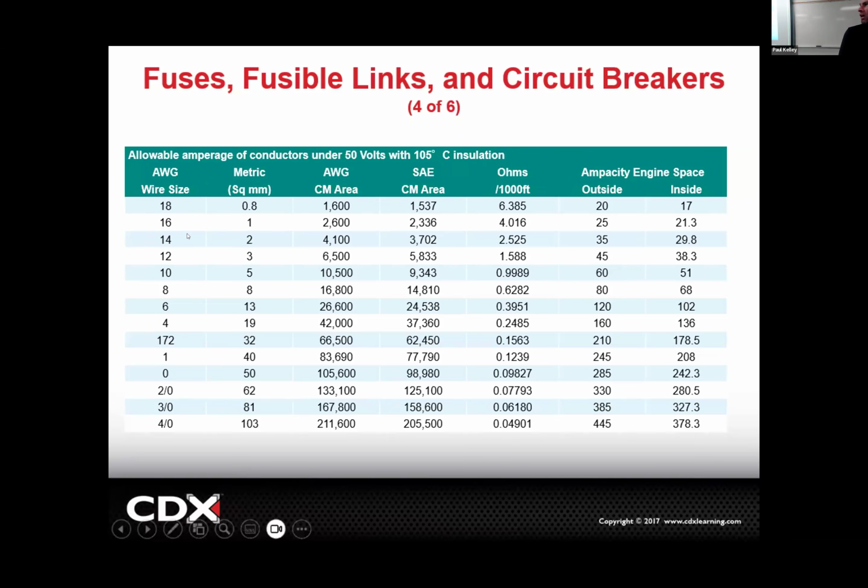Well, the 14 gauge wire would be an upgrade because you could run potentially up to 35 amps. Even if you only need 25, maybe rather than going to the 18, you just bump it up to a 14, right? So rather than a small wire, you run a big wire. That wouldn't hurt electrically, that would make sense, but financially it wouldn't. How come? Which do you think is more money? Exactly. Which do you think weighs more? Which do you think takes up more space in that wire, in that harness? So you have to understand, when the vehicle's made, they don't just put in bigger wire just because.